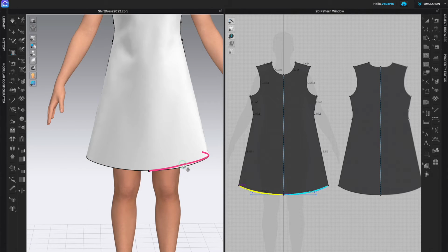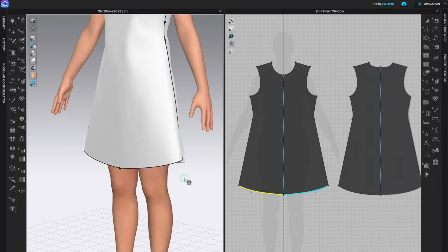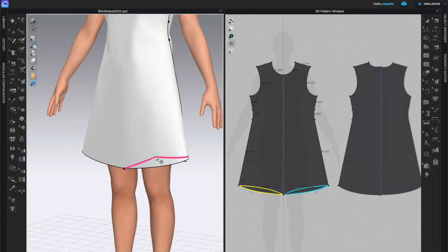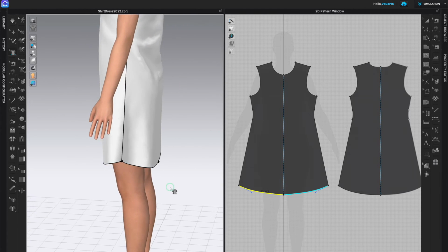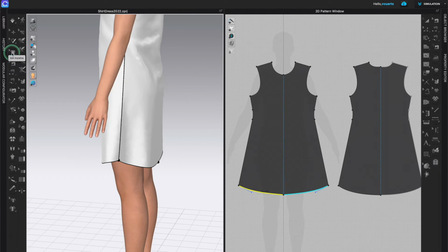And the edit style line is going to allow you to move a segment in the middle of it. So the segment points stay the same, but it changes the curvature and the line of it. See what's happening? Even though it looks like an angular point in the 3D window, it really is curving it. You can see sort of the preview of it in the 2D window when that happens. So I'm going to Command Z to undo that. So that moves and changes the curvature of a segment.